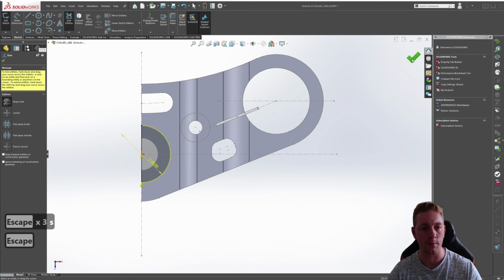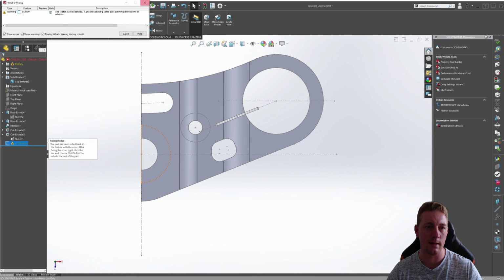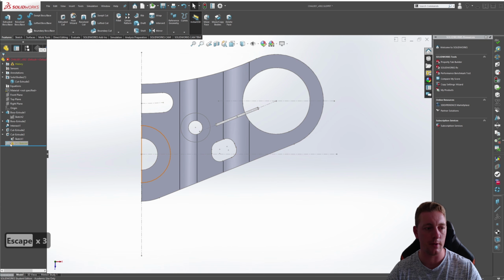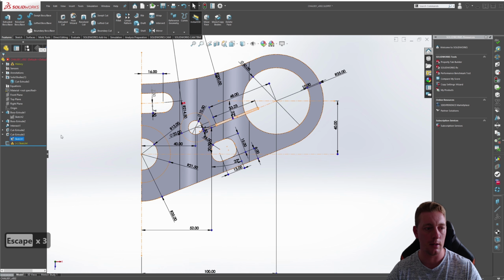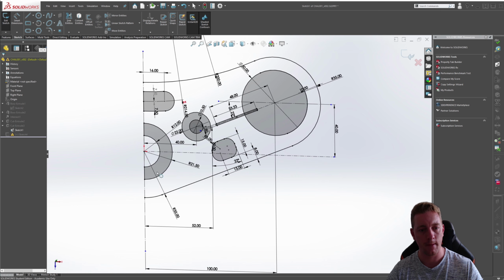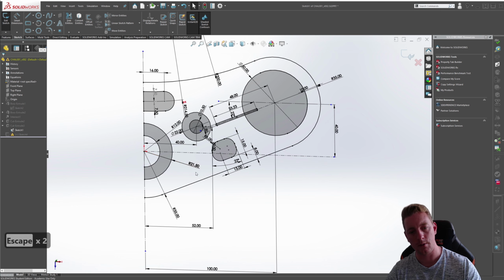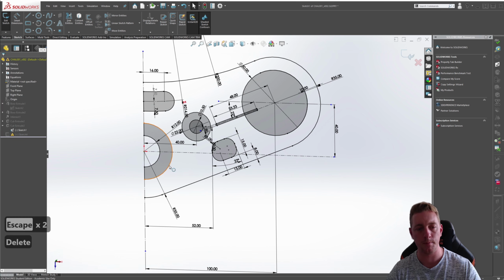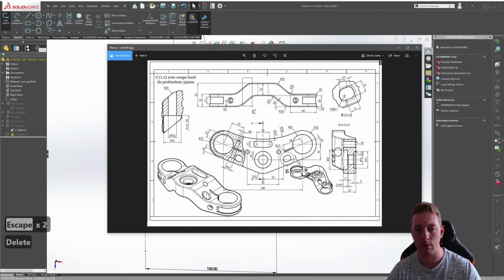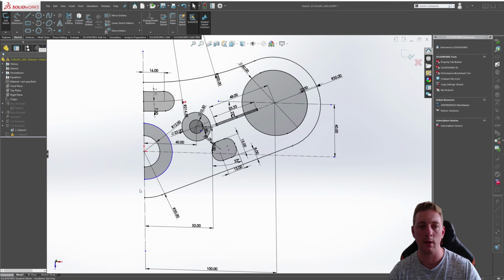That creates our profile. Now it's having a little bit of an issue because it is looking at that original sketch. So this one here, we're actually going to get rid of, or we can actually just change the size of it, what it should be. So this one should have been this side here, which is 50 divided by 2 is 25.